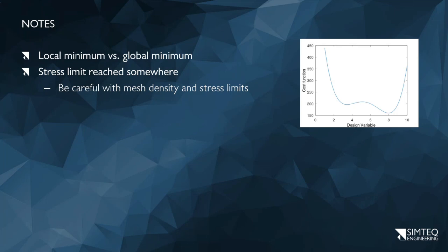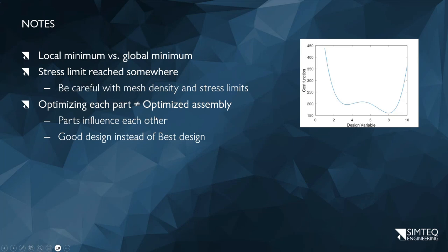Notice I said stress, but in general, we don't have a single stress. We have stress per element, effectively stress per node for the whole model. So there's actually lots of these. But what we can typically say is the maximum, for argument's sake, measured stress in the model is less than X. So effectively, I'm not looking at a single point, I'm looking at everywhere in the model. So just beware of this. Include this in your initial specifications. So if you don't feel comfortable with 200, if the code says 200, make that argument say 170, 180, 190, depending on, well, your model, your mesh, how comfortable you feel with a slightly closer value.